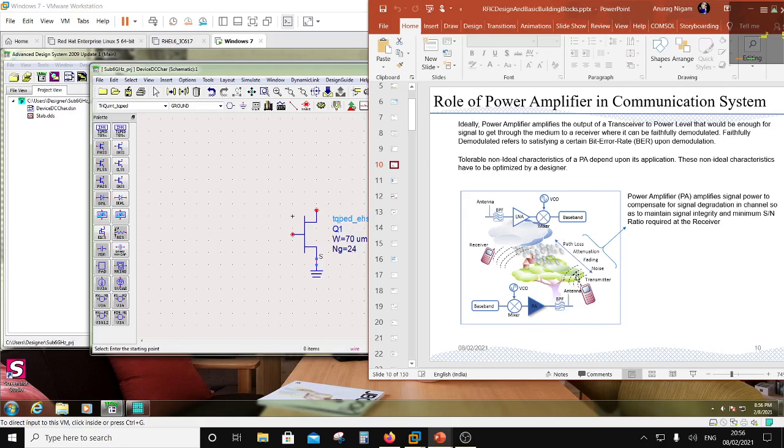So in this session and the subsequent sessions, I'm going to design this radio front end, and I'm going to use one typical process which is not a very modern process, because the gate lengths are 0.5 micron or 0.5 micrometer, right? So this is a gallium arsenide process and the device is a PHEMT, right? So I'm going to use that just to demonstrate what is a low noise amplifier and what is a power amplifier, and also design probably a TR switch, right?